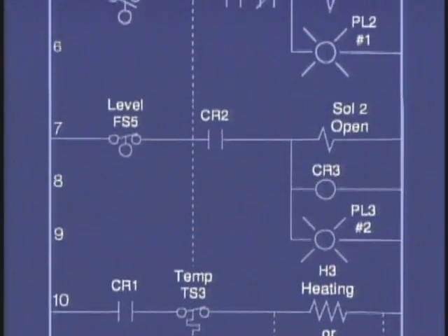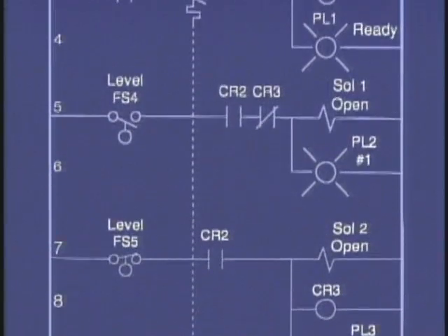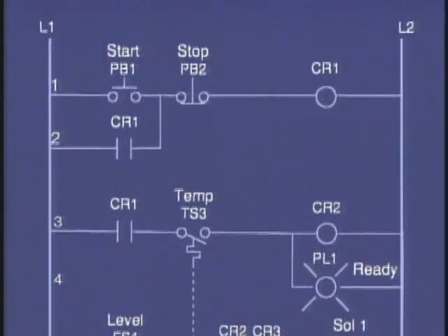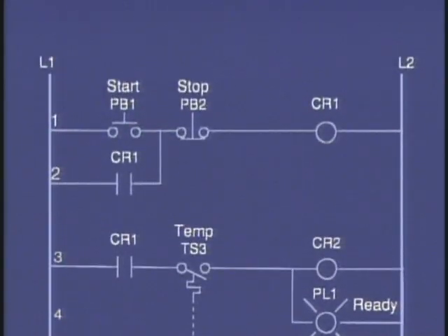By first inspecting the electromechanical relay diagram for inputs, we find that the real input field devices are those that receive input sensing control signals. For example, in the first line of the electromechanical ladder, we have the start push button PB1 and the stop PB2. These are, of course, two real inputs. We'll get to the outputs next.